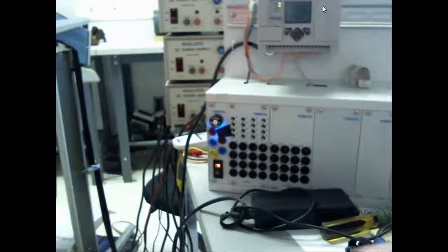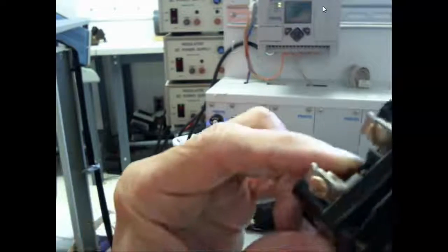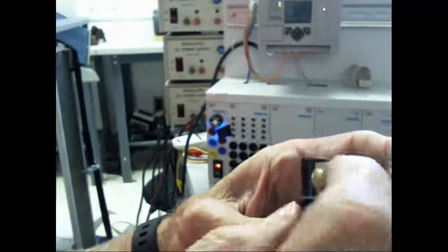We could pop this thing out right here, take this screw out over here, and the armature would pull out and then I could pull the actual solenoid out and replace it. So a lot of your industrial relays are actually repairable. We are getting away from where the actual contacts are exposed. Normally now they'll have a cap or something on this to prevent an accident. So these are double break contacts.